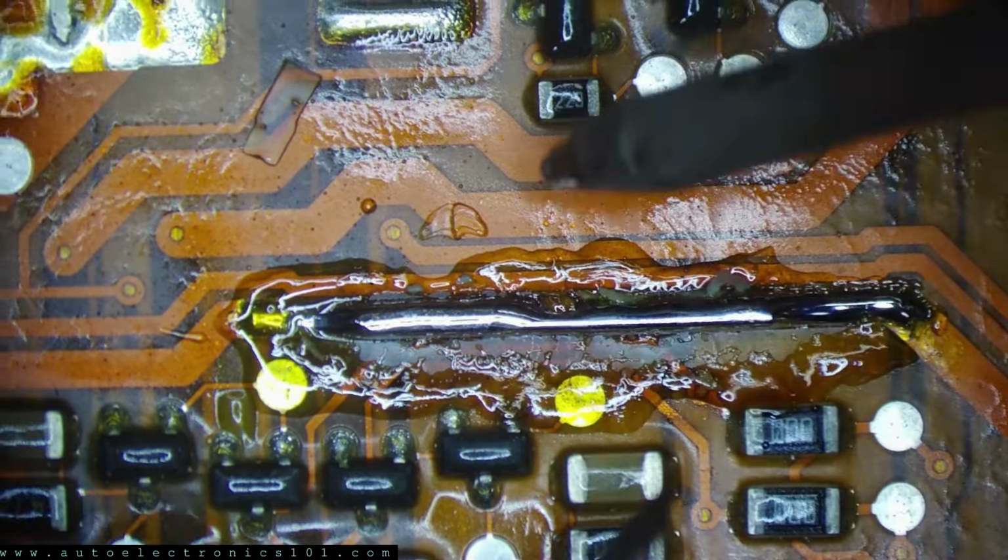Now, I guess I could put solder mask there, but I think I'm just going to lay this conformal coating over top of it. And I will let that dry while I do the capacitors. And then once the capacitors are done, and I check a few of the resistors that I like to check and the tantalums, and fix the logic stuff, then this guy will be all done and heading back to the customer.